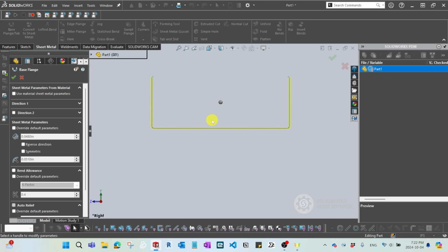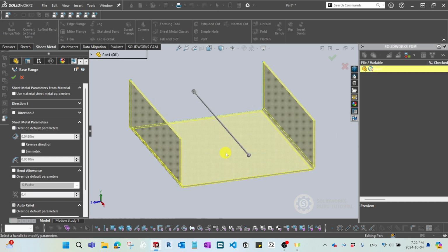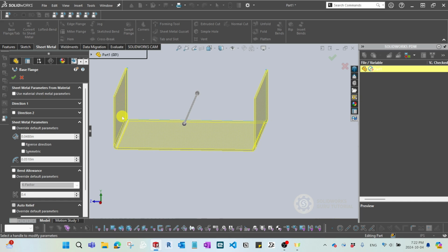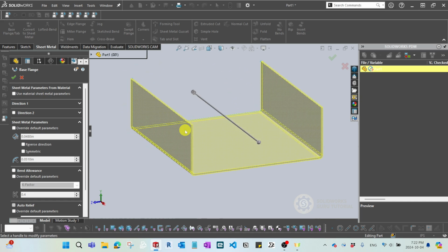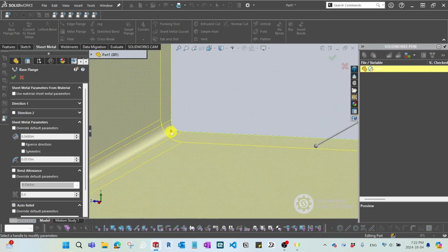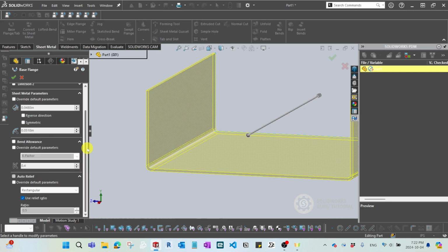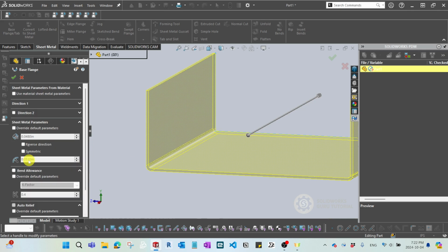And this is also another way you can create a specific thickness. You have to make sure not to create a closed loop. It's basically open lines. And even though we didn't provide any corner point, like a fillet, it automatically recognizes this as the corner point. So that's the point. It's recognizing the specific gauge with the specific bend radius that we provided. It's going to be auto assigned, so it's going to be 0.0510.